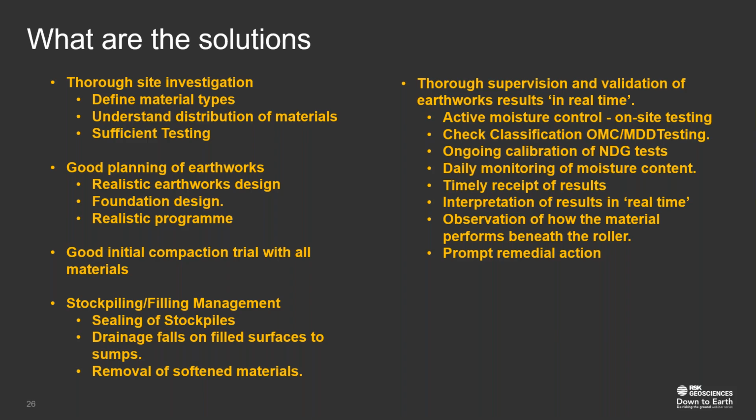There are many sites where you're working on clays and so on. It's not a good idea to start them in the middle of winter. The traditional earthworks season was St. Patrick's Day, the middle of March, for a pretty good reason, in that the weather improves thereafter and the ground will dry out. A good initial compaction trial with all materials is very important, although generally you won't be working to a purely method compaction approach.